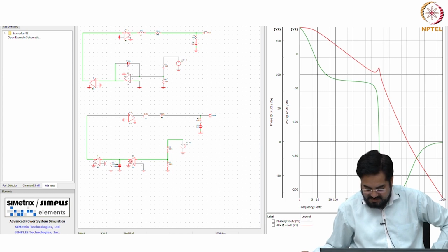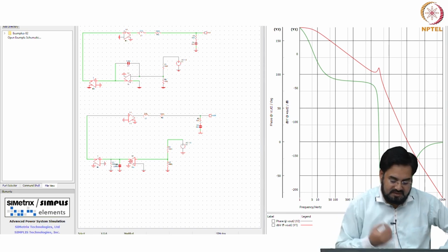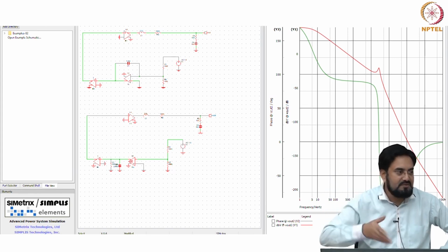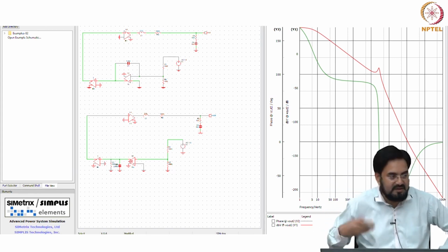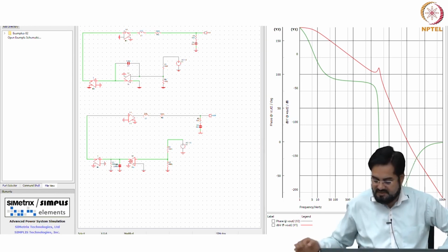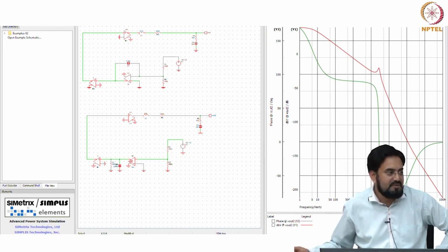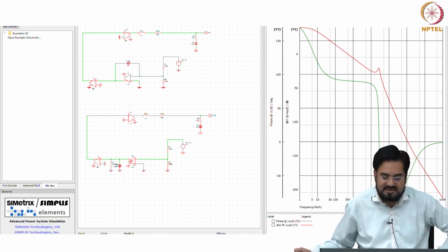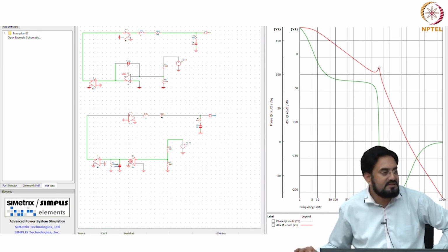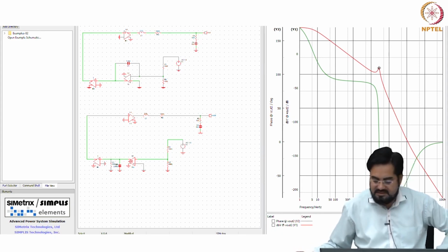You can see here the y axis is showing minus 83, because your RLC is lossy here because of your R loss, otherwise, if R loss is 0, it will cross to perfect 180 degrees, your total phase shift at resonance. So, you are only 7 degrees away from your total phase shift of 0 or 360 degrees, okay. And we have to make sure that here gain is much less than 0 dB, so that we do not get any oscillations or instability.